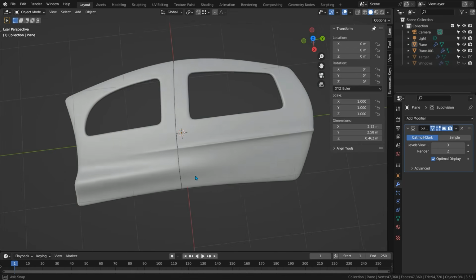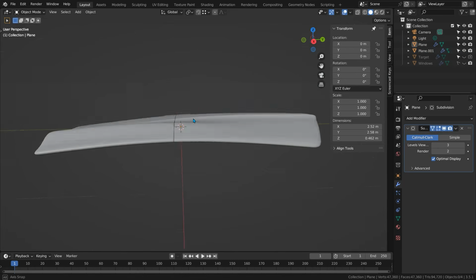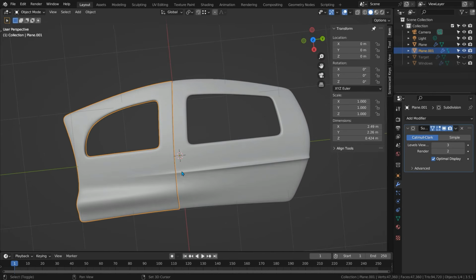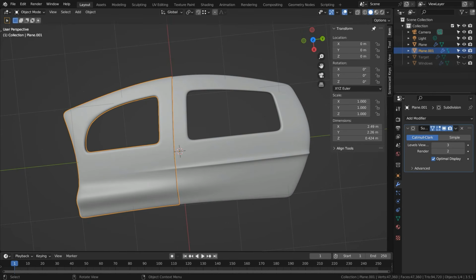And when they do close, they fit together like a jigsaw. And I would now start adding other furniture like mirrors and door handles and keyholes and all sorts of other modelling techniques for use for that, but that's for further videos. What I hope I've shown you here is that the curve tool is one of the most powerful tools in Blender when working on quad-based meshes which need to curve as they do in real life.